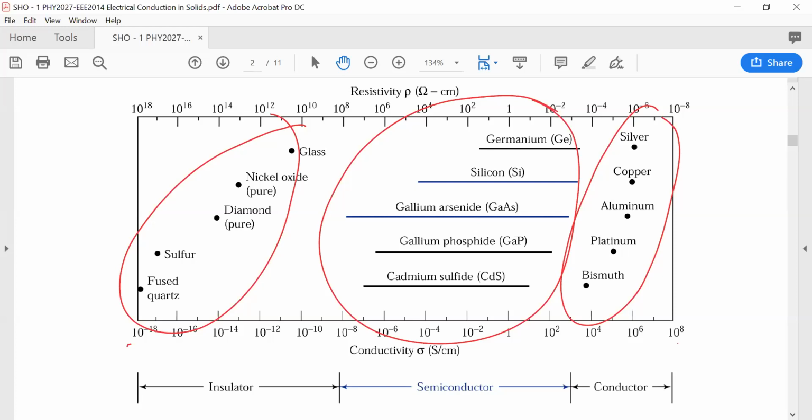So this means that not only does the carrier concentration and conductivity change, but it's possible to have more electrons than holes or more holes than electrons in the same material. When there are more electrons than holes, we call the material N-type. Remember, N is for negative charges and electrons are negative charges. And when there are more holes, we call the material P-type. P is for positive charges, because remember, holes are positive charge. And without this ability to generate N and P-type material, we wouldn't have integrated circuits, because all semiconductor devices exploit the physics of bringing together the N and P-type materials.